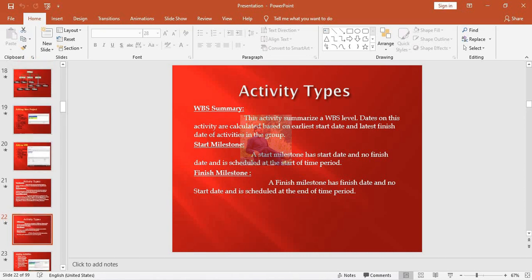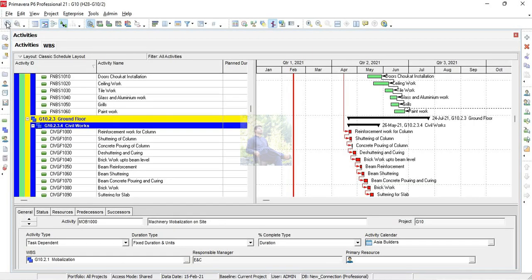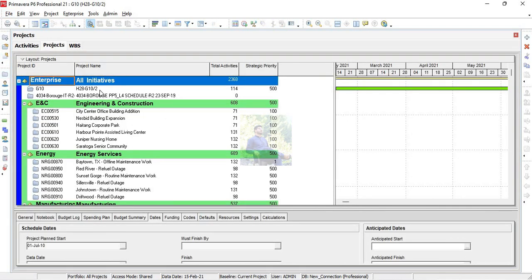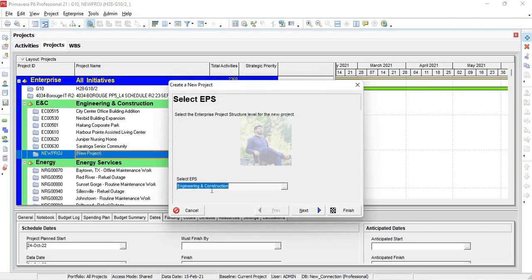Now we will see how we are going to add these in our PrimaVera. See, this is my EPS. I want to add a project into energy and construction. I will just click here and click add button. Select EPS, in which EPS I want to add this project.